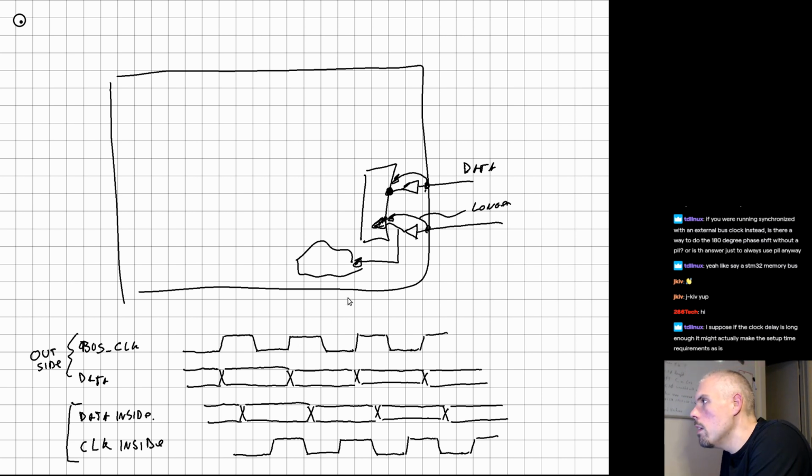Now, in that diagram, yes, exactly. That's what I was coming at. Is that at least in the ECP5, that's something that, because I actually had the case for RGMII, is that you have this case here, basically, and the clock delay. I don't remember the numbers, but it's substantial. Like it's 3 or 4 nanoseconds or something, which is basically enough to meet the setup time of this. And so you don't actually need to delay anything. You can just capture the data as is with the rising edge, and meet the timing.